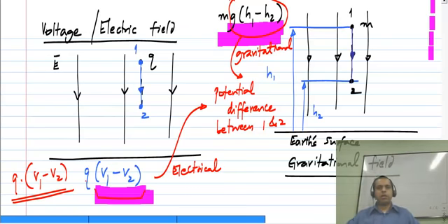So what is the bottom line here? Instead of dealing with charges and electric fields, we deal with currents and voltages. You can see that these are some sort of aggregated quantities. Current is basically the total amount of charge that is flowing through the wire or across the surface in general, but we'll consider them through wires and elements. And similarly, this voltage, also you know that the mathematical definition of voltage is the integral of the electric field. So basically, a voltage difference between 2 points represents the energy gained by a unit charge by going from the first point to the second point. So we'll deal with these things instead.